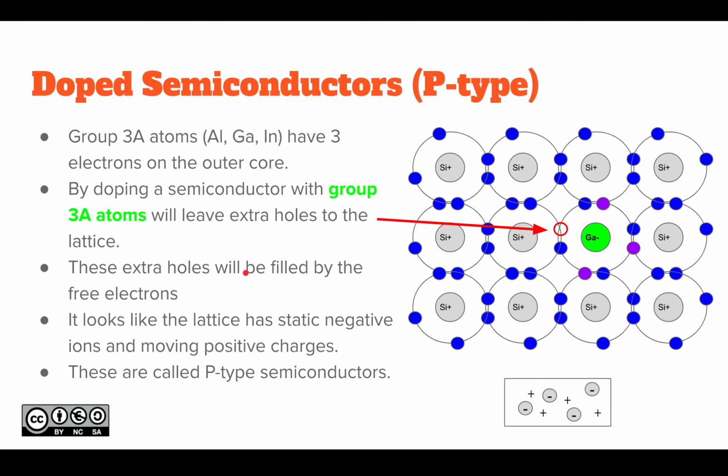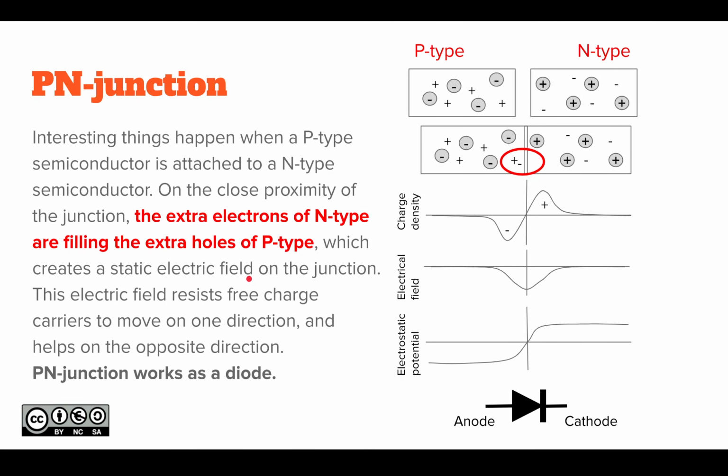And we have negative charge carriers and positive charge carriers. So what's the big deal? The big deal is a p-n junction. That's where the physics actually starts. How to make that p-n junction practically is that you take a p-type substrate, a silicon substrate, basically a plate, a standard 0.5 millimeter thick plate, 8 inches wide. 8 inches is 20 centimeters in diameter.